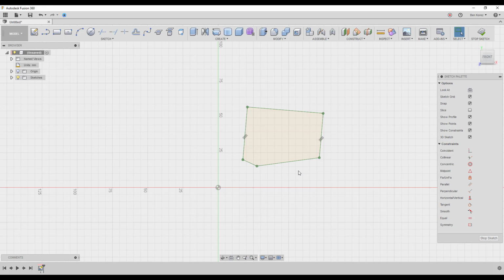Most of the time we're not using it because the models that we are building are more dynamic. We're changing them along the way. So that's why it's not going to be a good idea in most cases to use fix. Sometimes it's good to have it. For example, when you're importing a CSV file, it's going to be fixed, a green color, if you notice that. And if you're wondering why you cannot change anything, that is why. So you're going to have to either select everything or select only one part of it and do unfix.